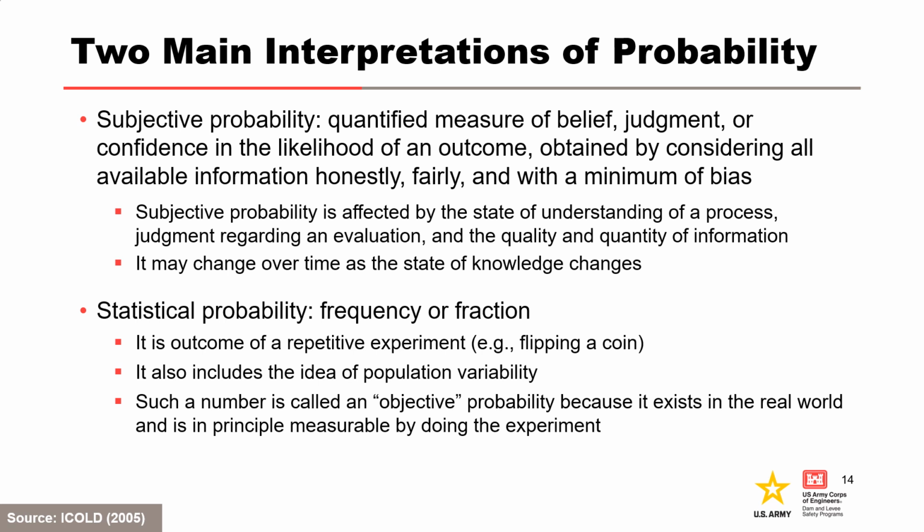Statistical probabilities can be thought of as the outcome of a repetitive experiment. Such statistical probabilities are covered in the Best Practices Training course and are used heavily by the Bureau of Reclamation in their risk assessments. They have statistics for their inventory on the rates of observed initiation, and they adjust those rates up or down based on factors specific to the dam being evaluated, and from there they arrive at a probability estimate. ICOLD, the International Commission on Large Dams, has statistics on dams worldwide which can be helpful.